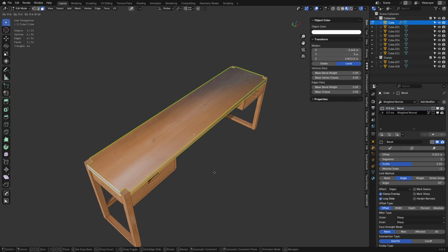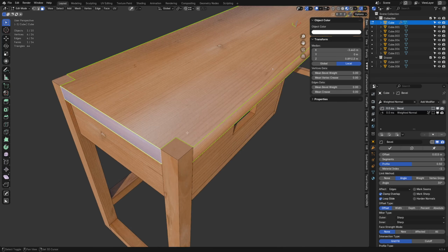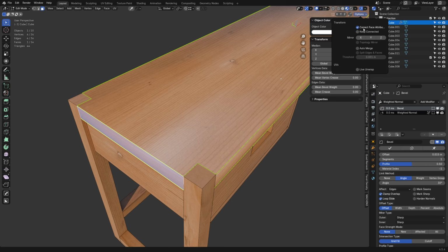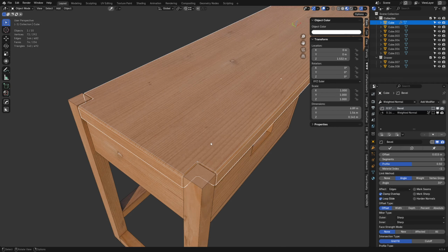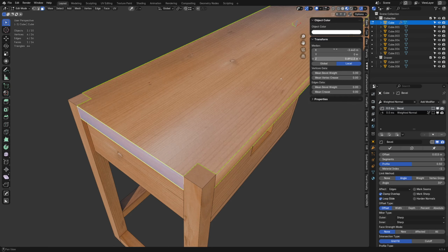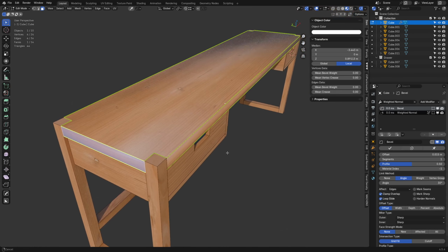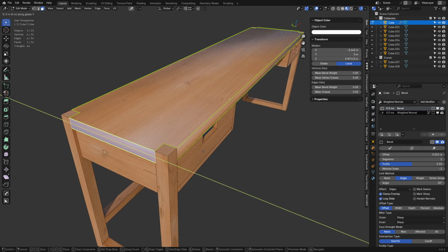And it's going to really mess up your UVs. But if you turn on correct face attributes and use keep connected as well, more than likely, sometimes you can try it off. What keep connected does is it makes sure that the UV islands try to stay connected together, the vertices of them. If you don't check that, they will absolutely be torn apart and you'll have to do stitching and other weird stuff in the UV editor to fix it. But turn it on, keep connected. If it works fine, use it, keep connected. Otherwise, rip them and turn it off.